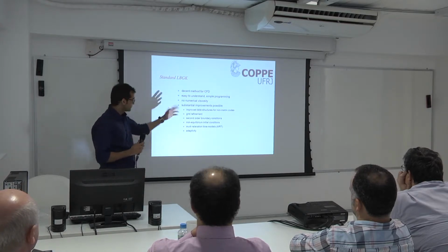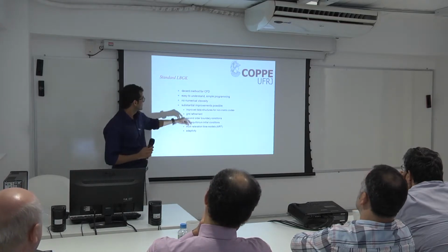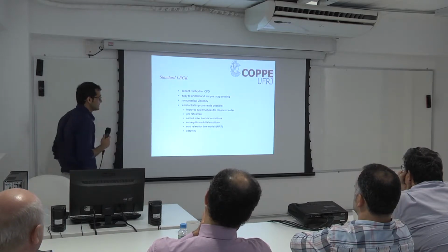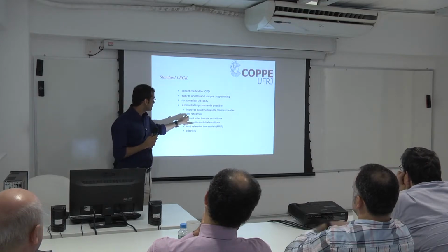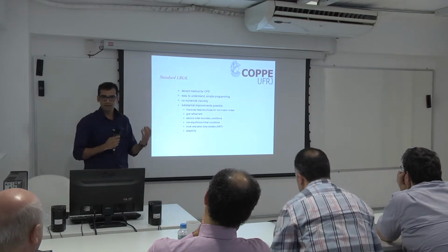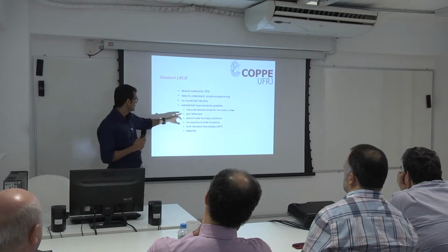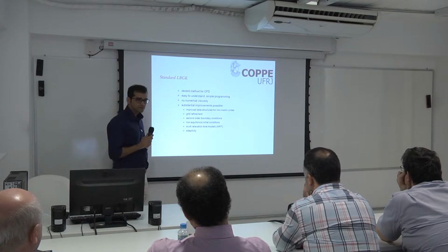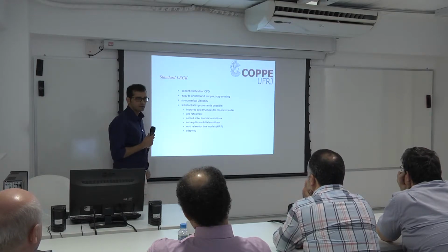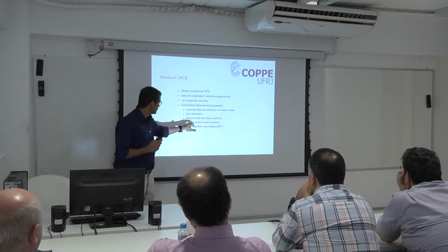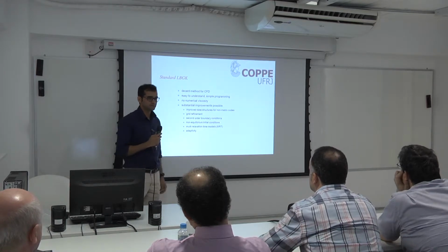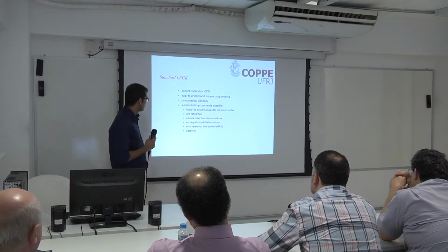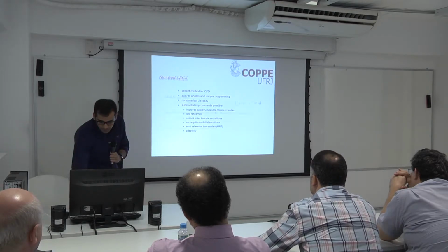No numerical viscosity, I'm repeating it. Substantial improvements possible: improved data structure for non-matrix codes. Grid refinement. It's a very good facility given with this method, a virtue of this method that you can do this very easily. Second order boundary conditions. Non-equilibrium initial conditions that occur due to the collisions. Multi-relaxation time models, you can also do that. And adaptivity. It's very easy to adapt.